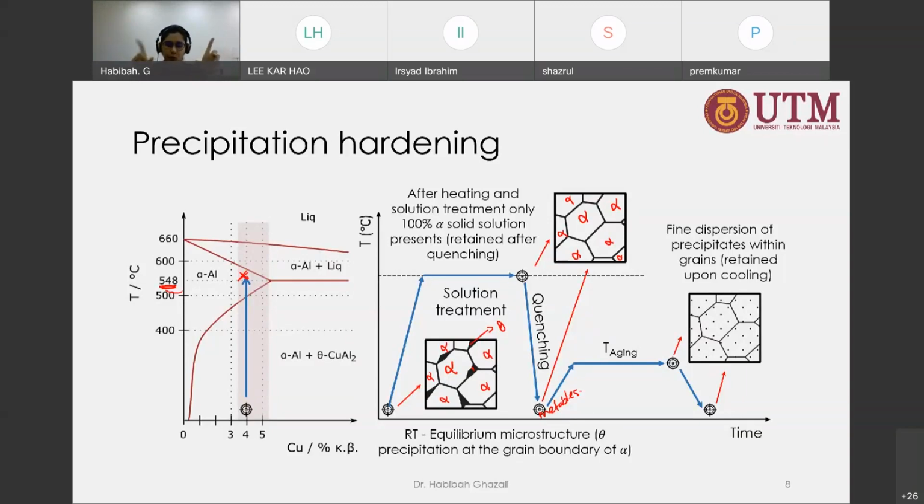So when he came back on Monday, after he left that specimen in that lab for 24 plus hours, he continued with that hardness test, and he discovered that the hardness had increased significantly. So that is when they discovered that if they leave it at a higher temperature, but not too high, it will allow that metastable phase to become stable by creating these short-range precipitates all over the matrix.